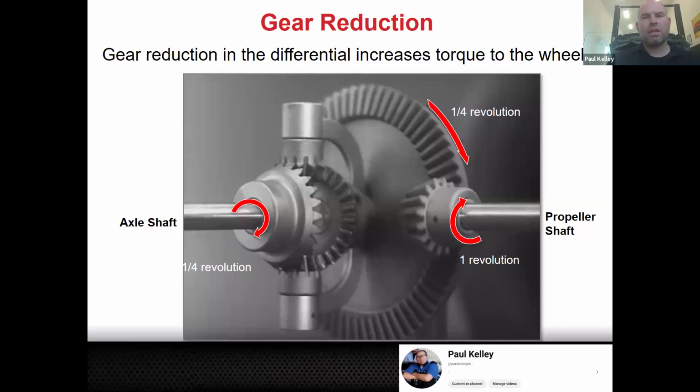So that's the positive. Now, if you don't believe this actually will turn backwards, I'll help you to understand it. That was a very difficult thing for me to visualize. If this is turning backwards and yet the whole axle is turning forward, how does that work? Well, think about it. Let's say this thing turned a quarter of a revolution forward. That meant all this turned a quarter revolution forward, but this little gear turned a 16th backwards. Overall, though, it's still going forward.